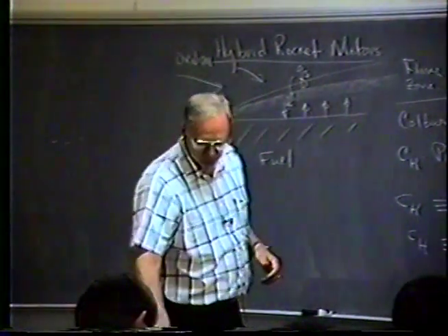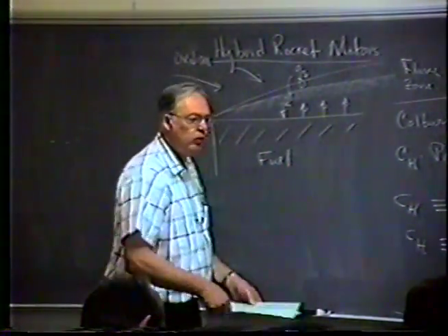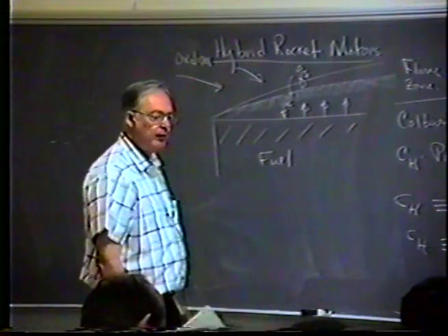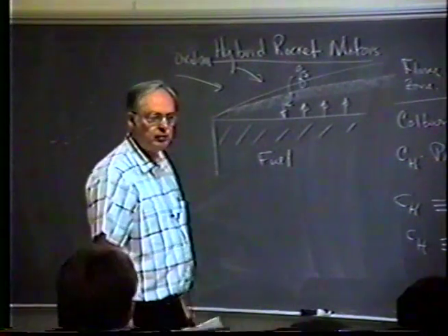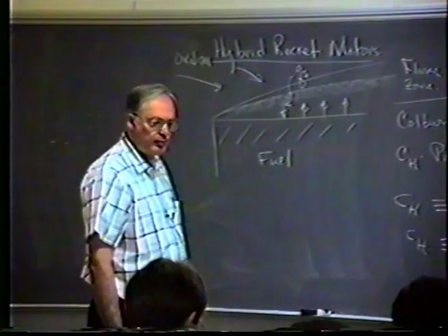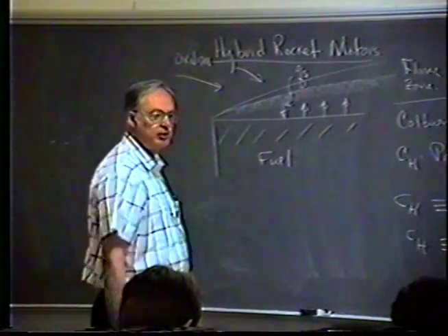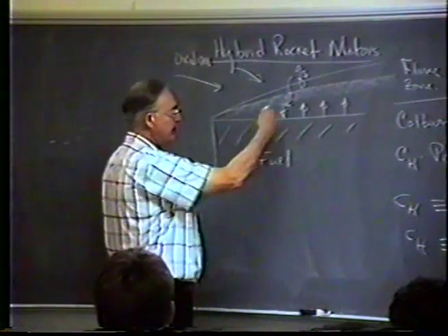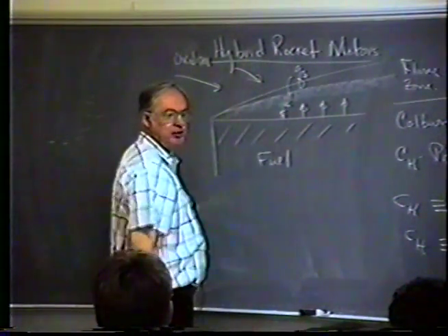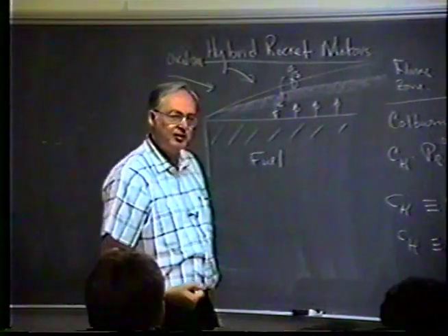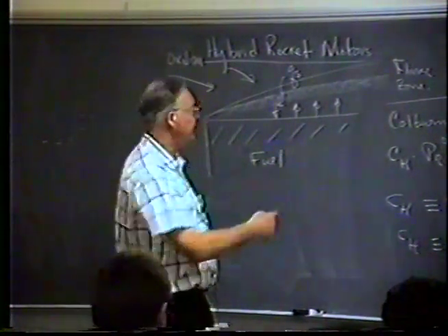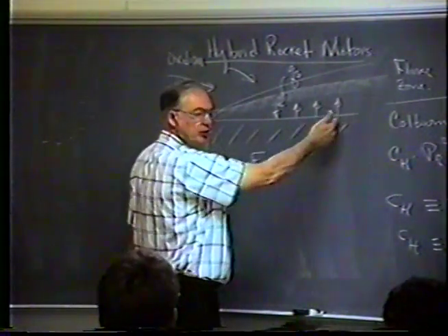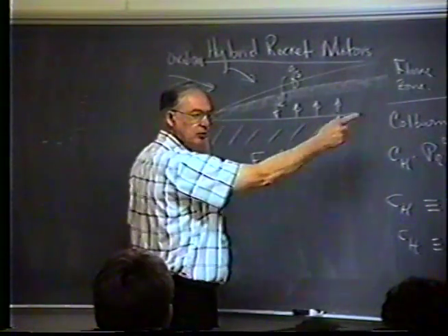If I remember some of the things I read, in solid rockets, it said that spinning the rocket burned it faster. Would the same thing happen with a hybrid? Probably, because of the forces applied to those gases. And if you have a liquefied metal, of course, that keeps the hot liquid metal near the surface, or brings the burning liquid near the surface. So it diminishes that distance. Anytime you diminish the distance between the flame zone and the surface, you're going to increase the heat transfer.